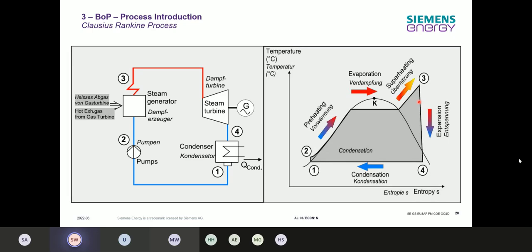So what's happening? My pressure is getting reduced, my temperature getting reduced, the steam is getting expanded, and we are transferring the energy from the steam into rotating energy onto the blade, onto the rotor, and then transferring it with the rotor, the rotating energy, into the generator. And inside the generator, we're producing then electrical energy, and this electrical energy will be sent to the grid then.